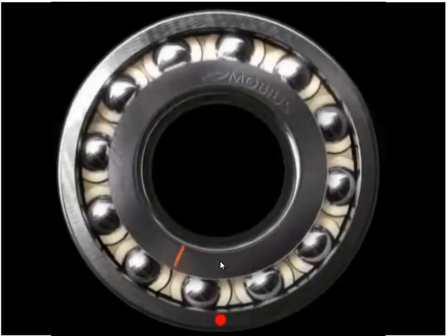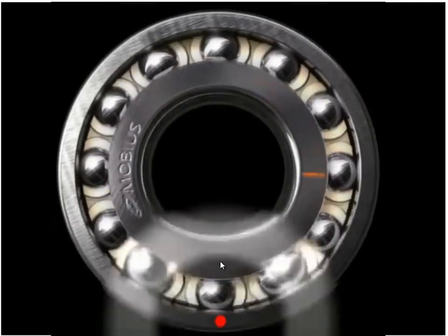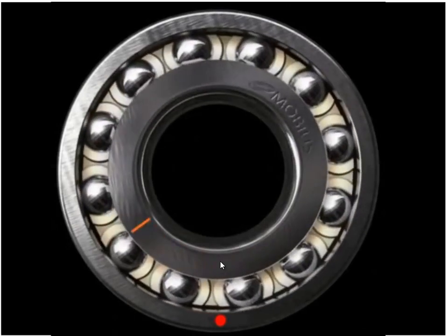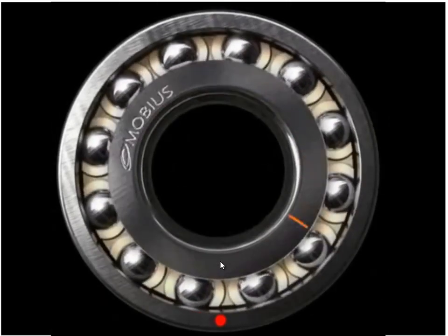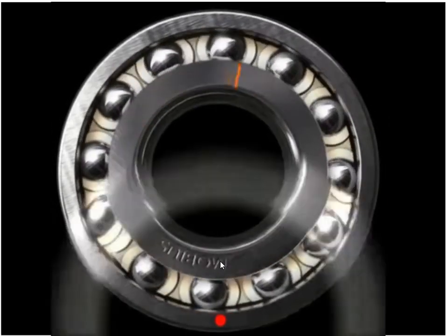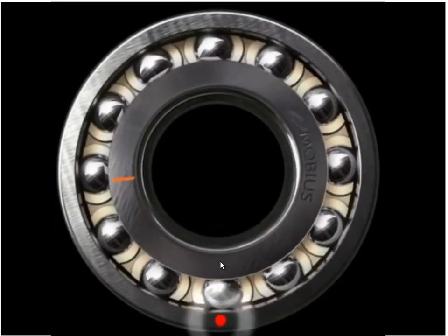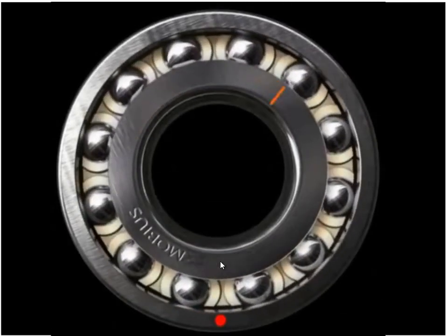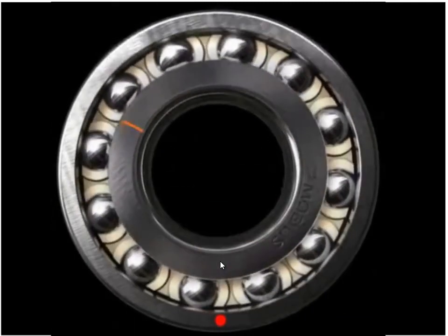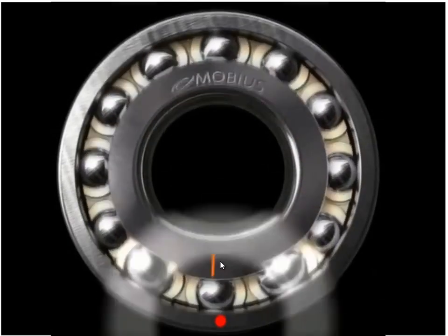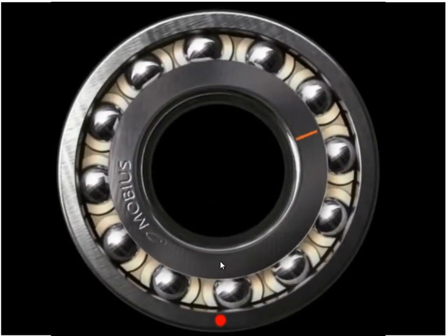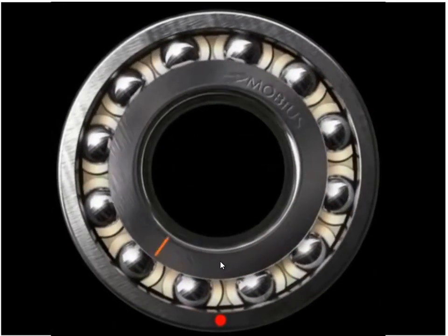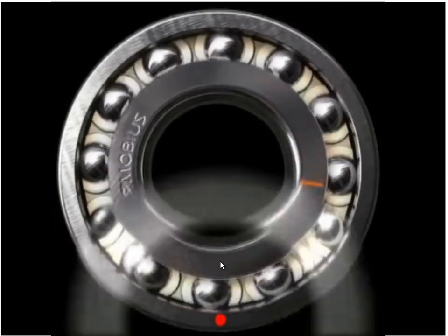Now there's a lot more I could say on this topic, but basically we can detect that because at the very earliest signs of a problem, either inside the bearing or with gears and other sort of metal-to-metal fault conditions like looseness and broken rotor bars, in that earliest stage we may not see any normal vibration. The amplitude is so low, the frequency is so high that we don't see it in our normal measurements. So we need to use a technique that looks for problems like this.